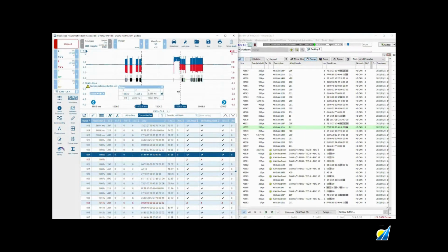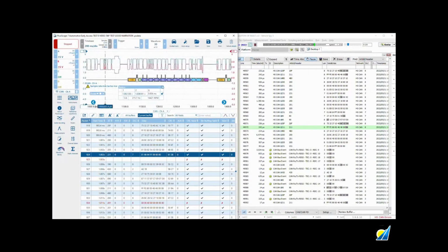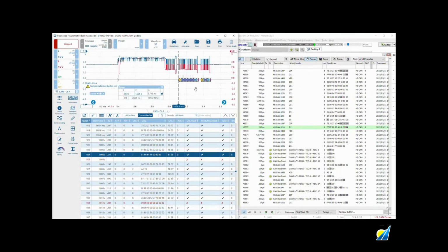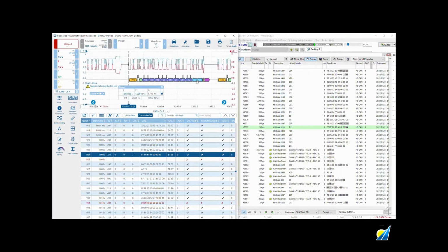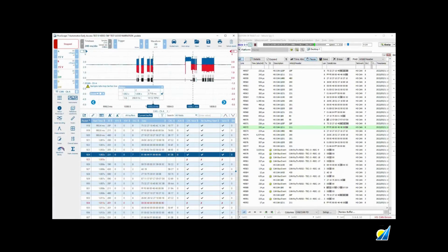And we move now to the next successfully transmitted message, which was 190. So between those two incidents, we've got 3.719 milliseconds, and there they are. So a successful message, a CAN error, and then another successful message here. So there's the gap, and the next message was 190. Let's just zoom in just to clarify that. 190, there it is. You'll find actually if you hover over the frame, you'll be able to see the message. There it is, packet 926, and the data as well.